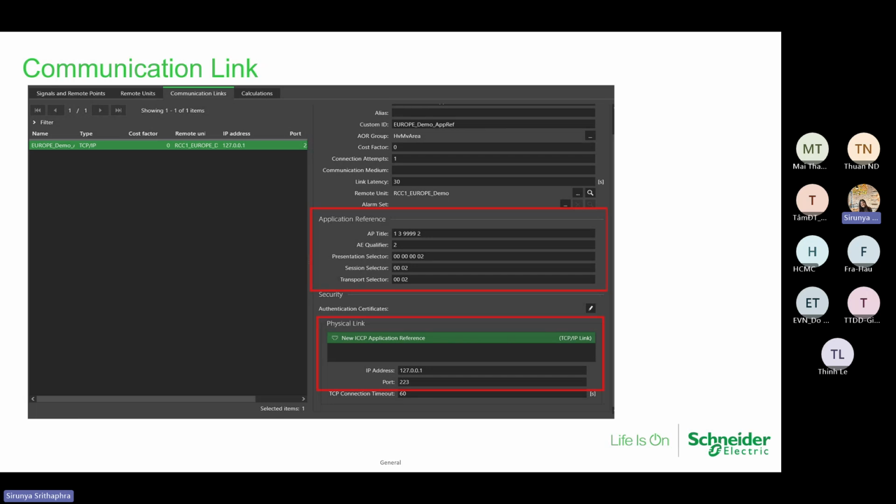So you can look at their existing ADMS. Their existing ADMS is connected to the RTUs, and we link by ICCP, whatever data they have already there. We can get a subset of it, the one that we are interested in, and we can use. And I think what he says also is that some devices like DRs, if they're not connected to ADMS, we can directly connect. If it's IEC or Modbus, something standard that we already agreed on, we can directly connect.